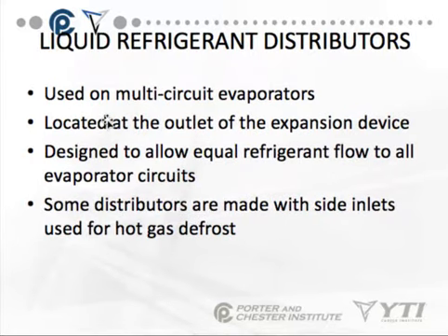Liquid refrigerant distributors are used on multiple circuit evaporators. They're located at the outlet of the expansion device, and they're designed to allow equal refrigerant flow to all evaporator circuits. Some distributors are made with side inlets, which are used for hot gas defrost.